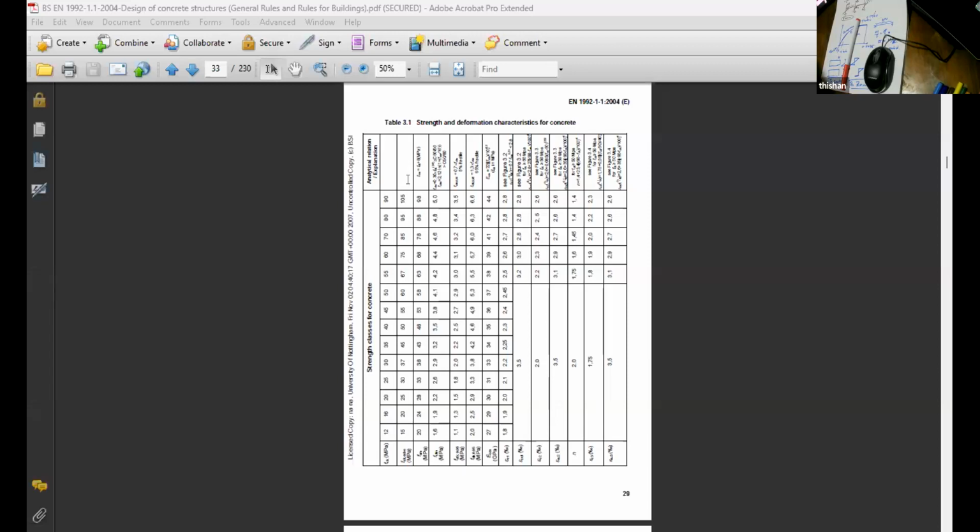Well, we had a problem. The costs were too much. Projects were becoming not feasible. So what we have done is, we have changed the foundation, done a more advanced design. But you might ask, how are you going to ensure that it's going to work? It's so simple. For piles, we have PIT, pile integrity test. We have PDA, pile dynamic analysis. We have maintained load test. So if you take a pile like 1.1 meter, 1.2 diameter, do maintained load test. Then do PDA on the same pile.